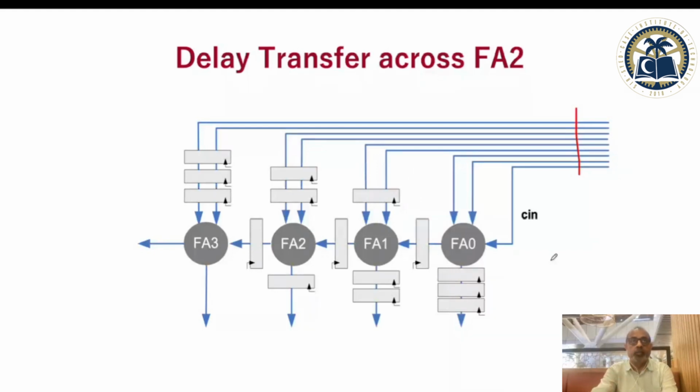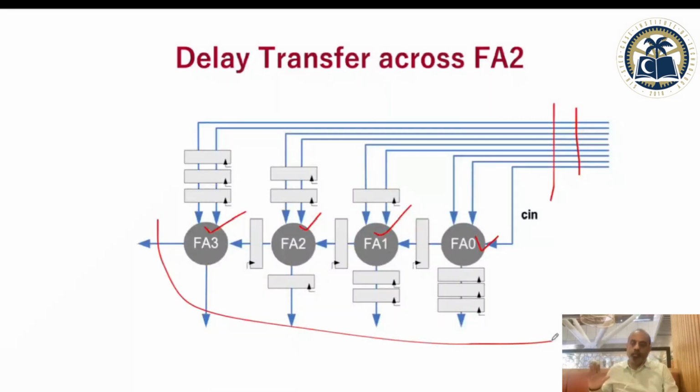So it becomes important that you are able to draw a design at a level of abstraction where the clouds which you want to break down into pieces are separately shown in your diagram. In this example we are just adding two bits together, but this may be bigger logic. What is important is that you draw at a high level of abstraction, draw the computations that you are doing into smaller clouds, in a manner where you see all your inputs and all your outputs, and then systematically get into the cloud, which is shown broken down into pieces, and keep leaving registers.